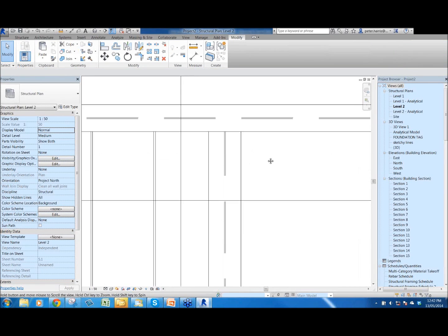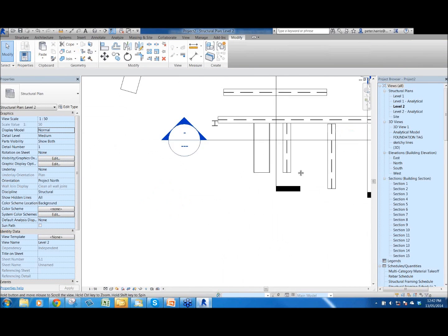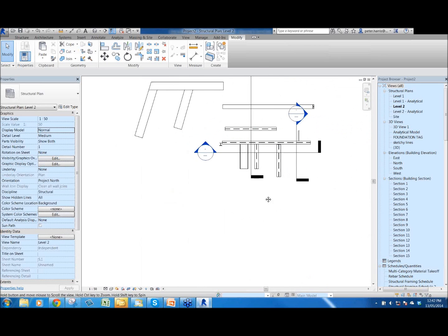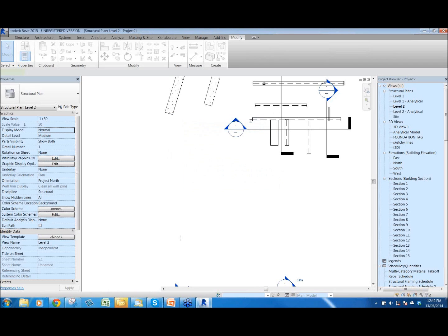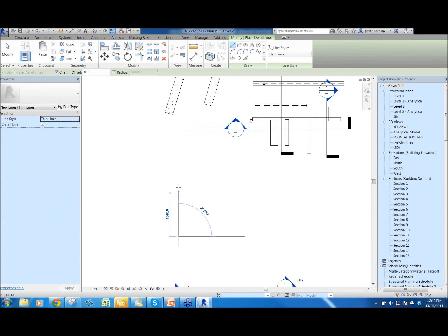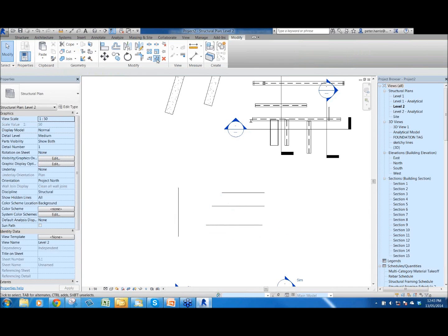Okay, and then one of the other final features is, as simple as this is, selecting, say, a series of lines, doesn't really matter. This can be elements, does not make any difference. Knowing you've now got the trim extend multiple, selecting the boundary, and then selecting a crossing window, and they can all extend. So back to, again, a bit more AutoCAD based, but still does make a difference.